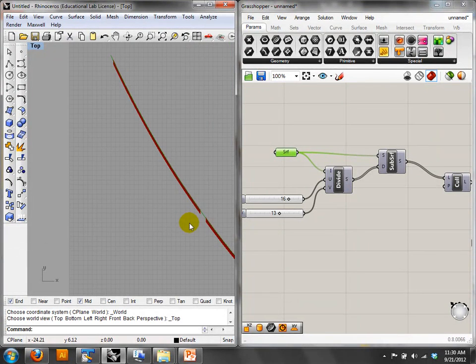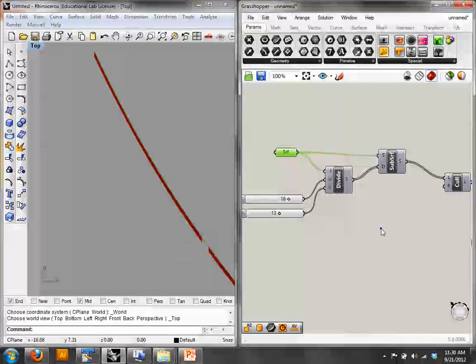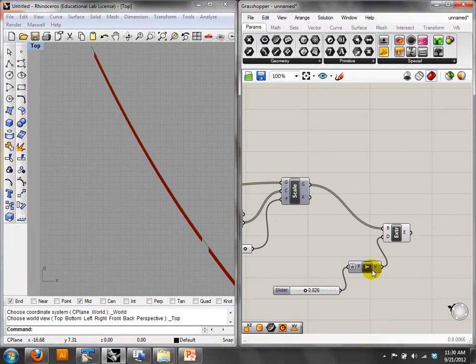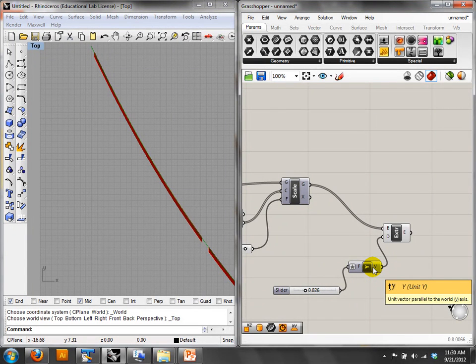But you'll notice something about it though, that there's kind of a bug. The way that it's extruded, the extrusions when I did this, are only in the y plane. And so what happens if it changes planes? What happens if it's pointing in a different direction? That's going to change those planes. So it's not actually variable. It's not parametric enough because it can't stand up to that. Okay. This is what you guys will do in week 3: take the ideas that you have and make them work in every situation or in most situations.